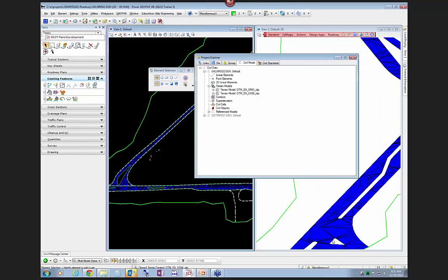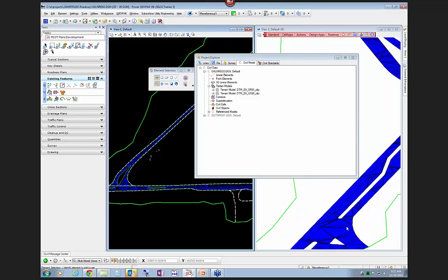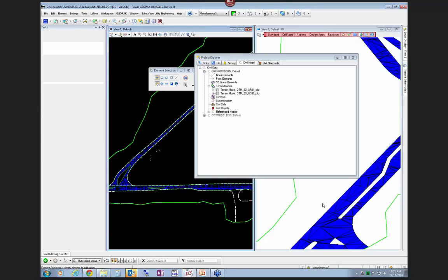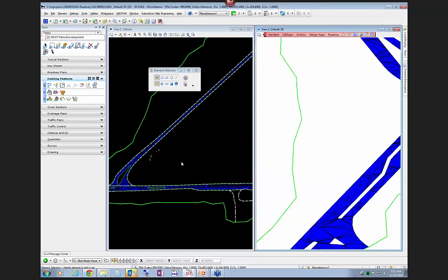Now, once you have these pavement areas delineated, because in here we have traffic separator, and here we have probably some type of a curb median, and then an island possibly over here. Again, your topo file is going to help you delineate what's what. So once you have those, then what we're going to do is apply what's called a surface template. A surface template is nothing more than depth and a feature to a terrain surface.